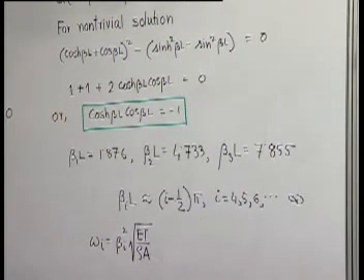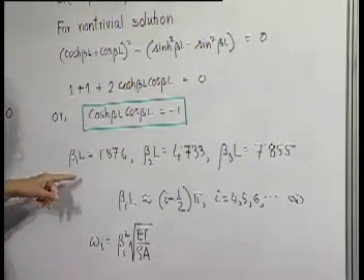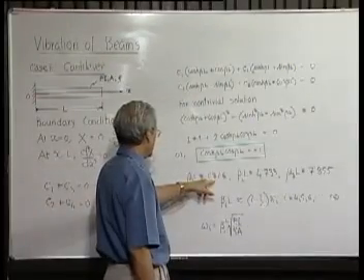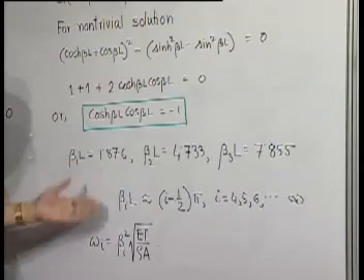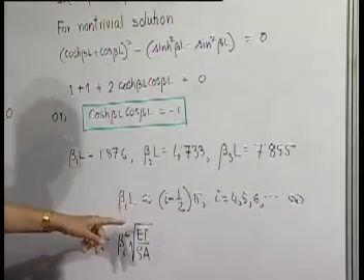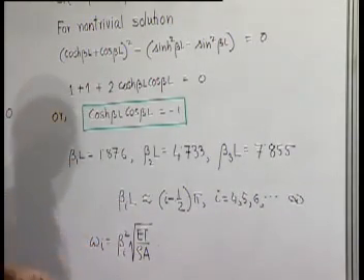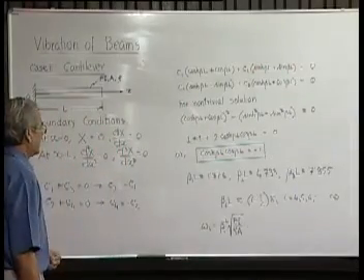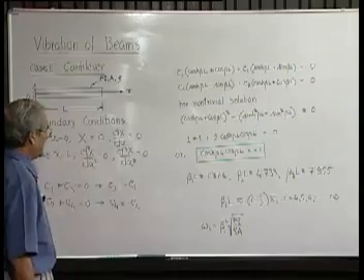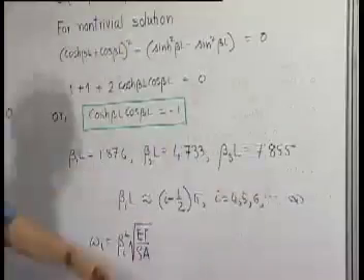Here if we find the first root, it will be approximately 3 point something divided by L, L square and this. So that is the natural frequency of a cantilever beam of length L, the second mode and so on.